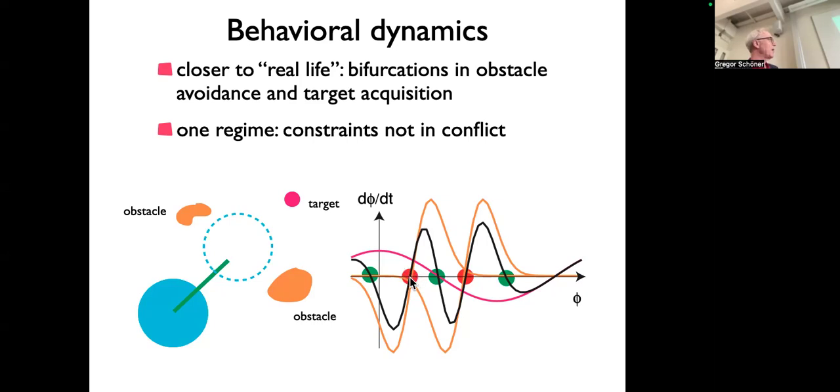So here, this is the repeller from the left obstacle, from the right, and the attractor in the middle, right? This is sort of an emergent attractor, if you want, on the outside. That's meaning going around the whole configuration. Emergent in the sense, you see, you have an obstacle contribution like that. It's sort of like a half attractor, right? If it goes to zero here, and this is a negative slope, so it's almost like an attractor, except that if you're on the right of it, then it's no longer attracting, but it's pushing you out to some heading. If you add just a little bit of attraction from the central attractor, it makes a real attractor, because the sum is the black line here, and then you see it's a real attractor because you have this repulsion from the obstacle plus a little bit of attraction.